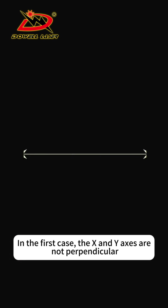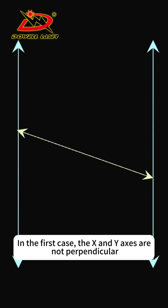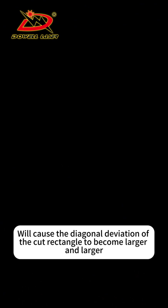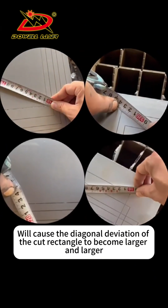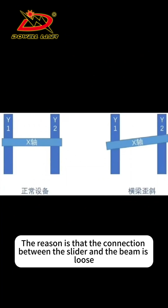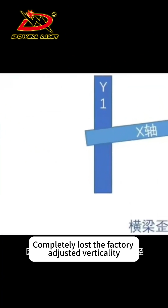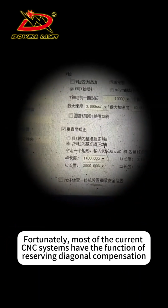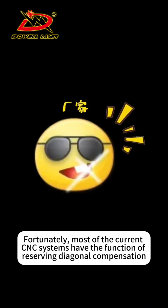In the first case, the X and Y axes are not perpendicular. This was very common on early split beams. It will cause the diagonal deviation of the cut rectangle to become larger and larger. The reason is that the connection between the slider and the beam is loose, completely losing the factory-adjusted verticality. Fortunately, most of the current CNC systems have a function for diagonal compensation.